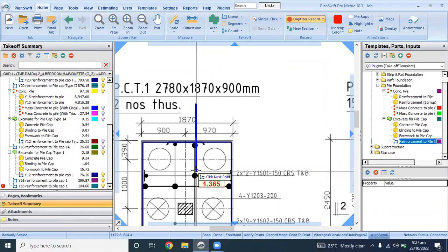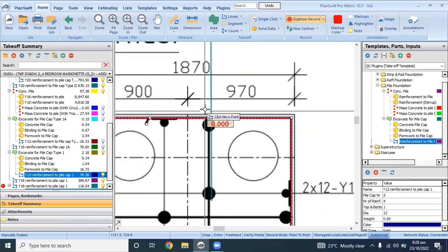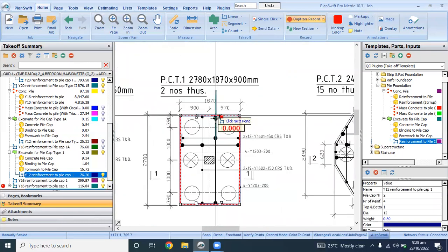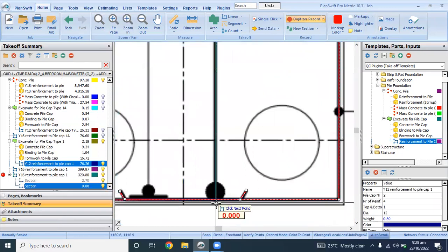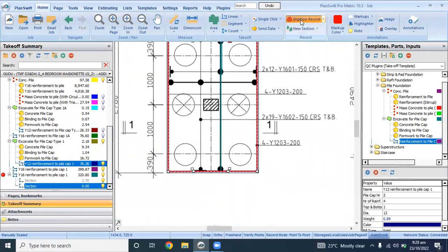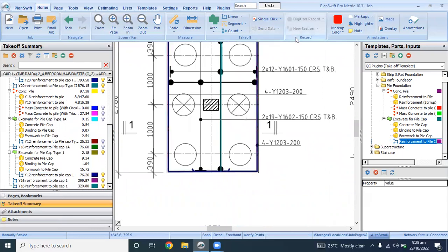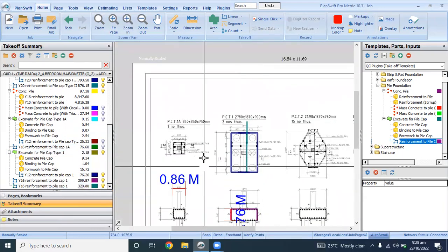So 1.52. So it's still okay. I've considered that bend by taking this length outside this plan and taking the main bar itself like this. So we've considered this one and drop the 2. Everything has been considered and calculated for.